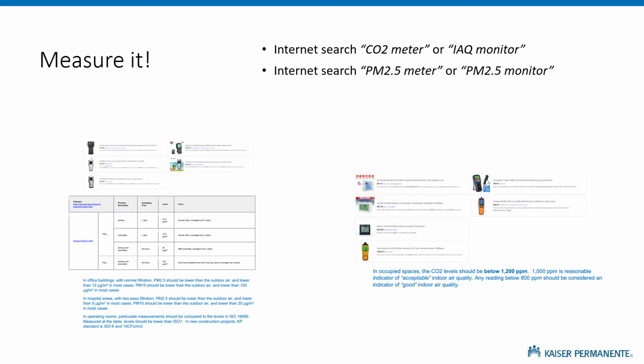So just to give the example, let's say that a facility is considering changing filters from MERV 8 to MERV 13. Okay, great. Start by going into the building and measuring how well the filters are working. Those indoor levels should be better than the outdoor levels, and on a normal day without fires, your indoor PM 2.5 should be 12 or less. In my office, it usually runs 5 to 9 or something like that. If it's higher than that, then maybe better filters would be useful, although you'd want to check first to make sure you don't have an internal source of contaminants.